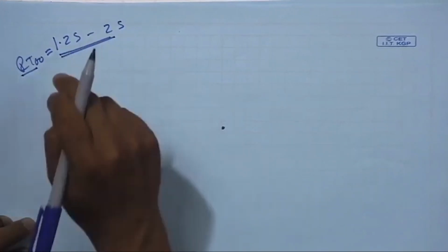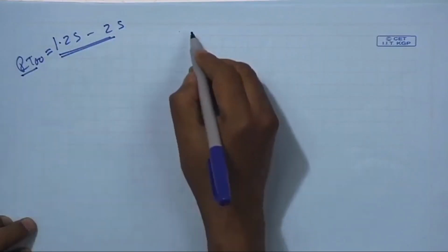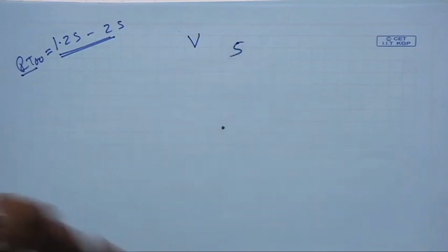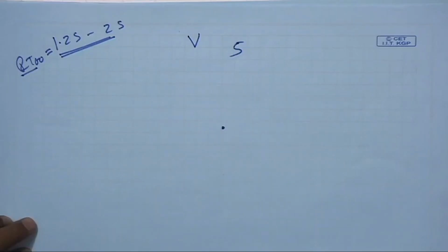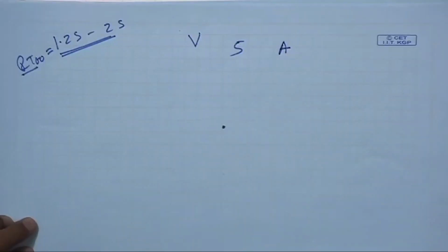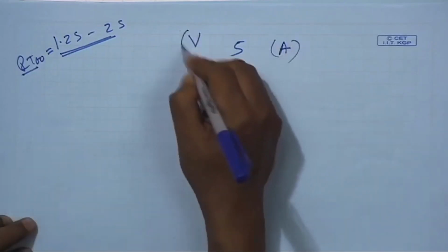Now, if I say within this range my RT60 should be, then what is given? Civil drawing is given. So, the volume I know, surface area I know, different surface areas I know. There is a wall, there is a door, there is a window, there is a stage, there is a floor, there is a chair. Everything's absorptivity is given and their surface area is given. Then I can calculate capital A, the average total absorptivity of the whole surface area.